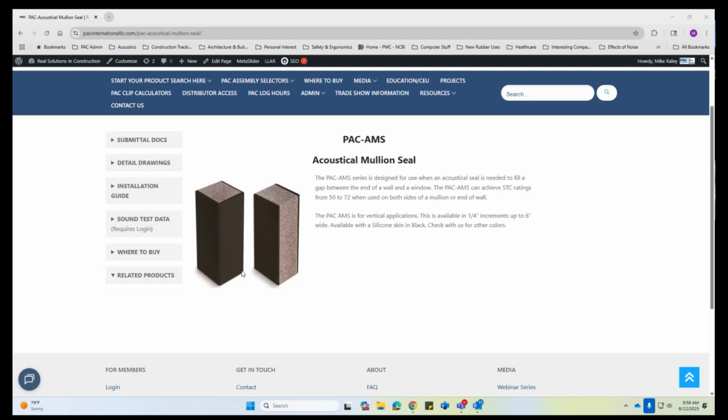Ken asks, can you touch on virtues of isolation versus constrained layer damping for transfer of energy? Okay, sure. So, how do I do this succinctly? Within acoustics, we have all of these different tools. We have acoustic isolation, we have damping, we have mass, we have insulation, in terms of fiberglass or these kinds of things. And they're all different tools that do different things, right? So isolation reduces the transmission of sound from one side to the other, because it allows this thing to move without making this thing move.